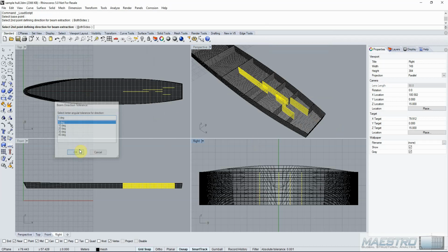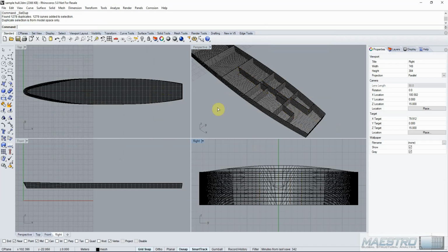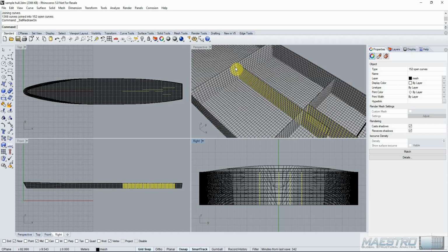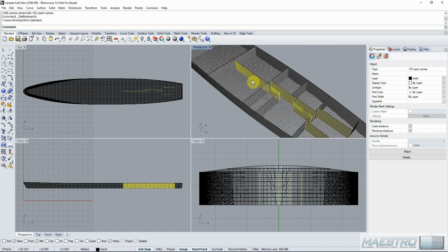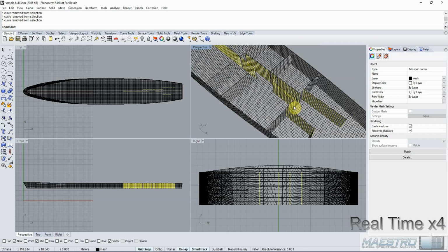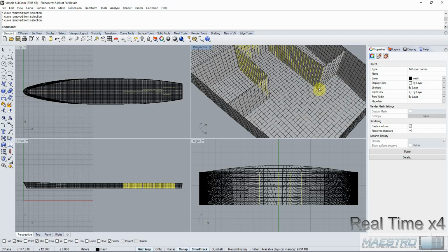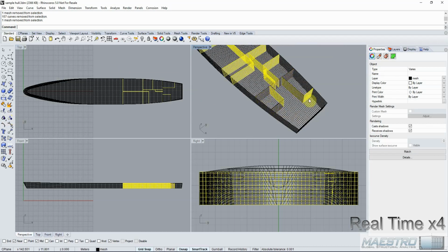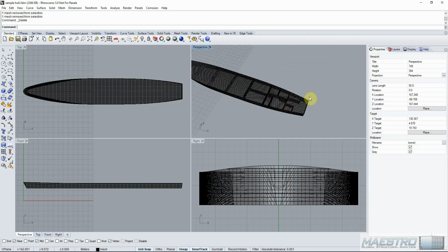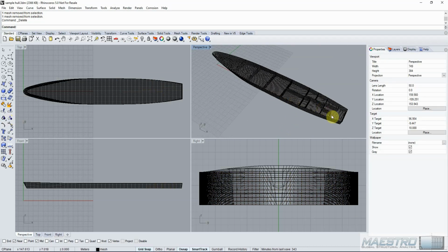For now, we'll make these vertically stiffened, although we could also extract the longitudinal stiffeners and simply use that other script to keep the X intervals for any vertical frames that we want to keep on these. But for now, we'll just do the same thing that we did on the transverse bulkheads. We'll remove polylines from the corners and intersections, make a group, and then clean up the extra polylines. So now we have all of our beam traces.